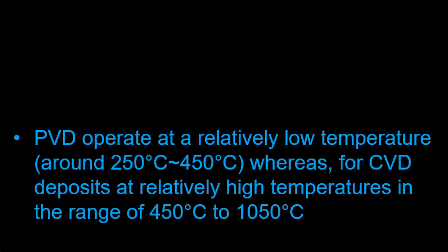Why is a high temperature required for the chemical vapor deposition process? Please note that first, the precursor material, usually in the form of a solid, or in a liquid injection chemical vapor deposition system in the form of a liquid, is heated in a stainless steel container, which is present externally. So it is converted into vapor phase or gaseous phase molecules. Now these molecules are transported by a carrier gas inside the reaction chamber onto the surface of the substrate.